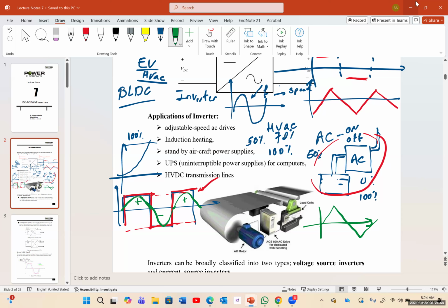And it's the signal that it produces. Obviously, it's better than the square AC. By the way, all of these are considered AC in terms because it's alternating current, but it's not a pure sine wave. So when you want to buy an inverter, make sure it's a pure sine wave.